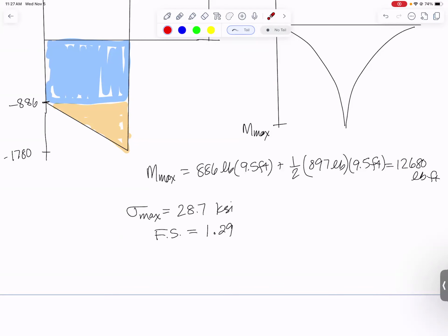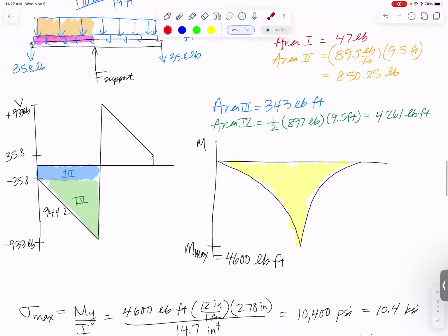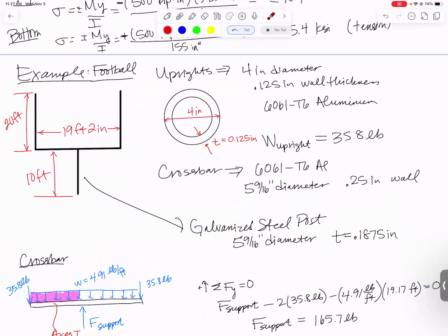The first is, if you see the students on the uprights in videos, they oftentimes start rocking this back and forth. They'll get this side to rock down and then that side to rock down. Whenever you add dynamic effects, materials fail sooner than if the loads are purely static. All we can analyze in this class are static loads, but once you add dynamics, failure occurs sooner.